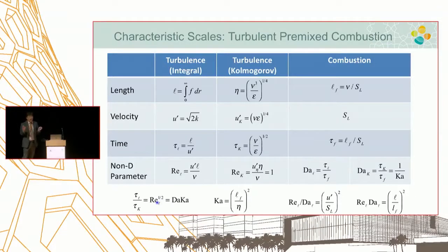And this is indeed the most challenging issue about simulation of large Reynolds number turbulence, because you need to capture the largest eddies and at the same time you need to resolve all the smallest eddies. So you can't do that. And the dynamic range gets larger and larger as the Reynolds number increases. So those are the basics of turbulence.